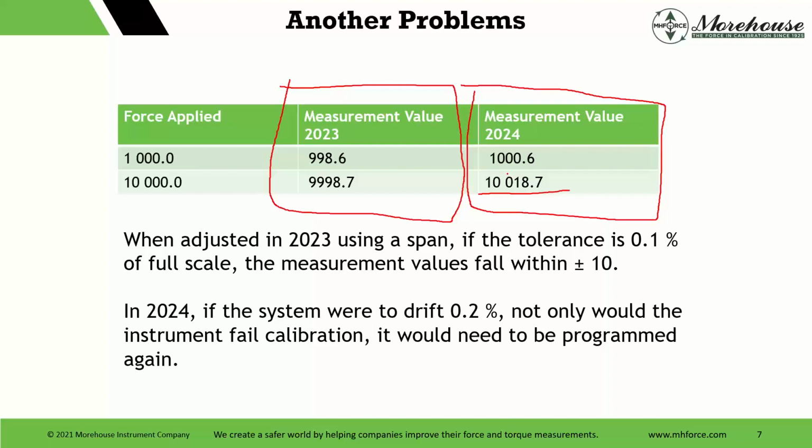It's the Deming funnel experiment. You can look it up. You drop a marble on something, and then you adjust the target, drop it again. And when you're constantly chasing these numbers or adjusting things, your overall uncertainties get much, much larger, as if you would just leave it alone and not adjust it.